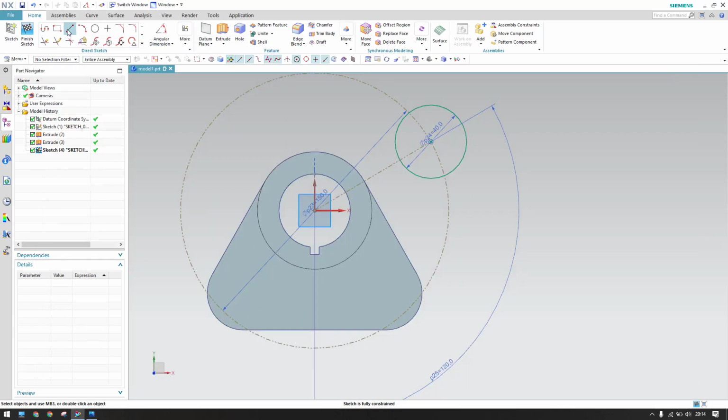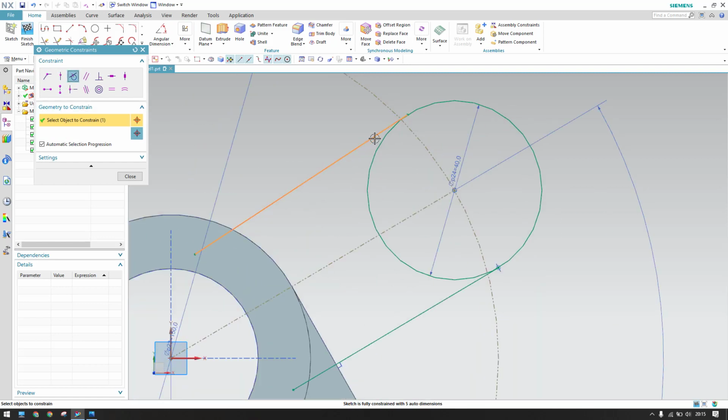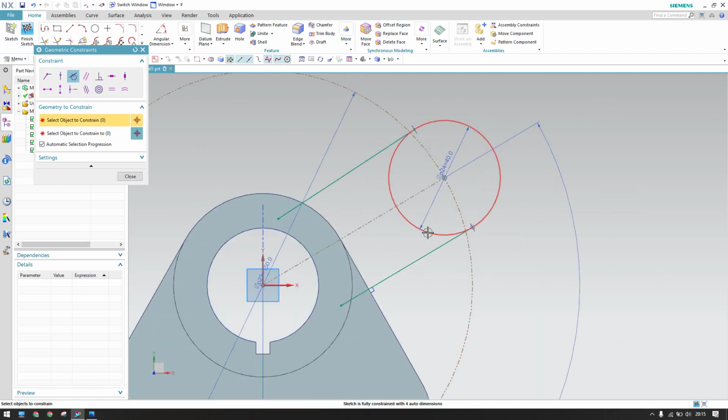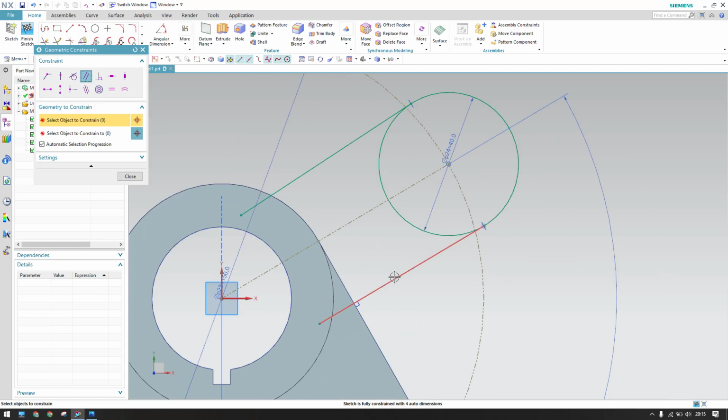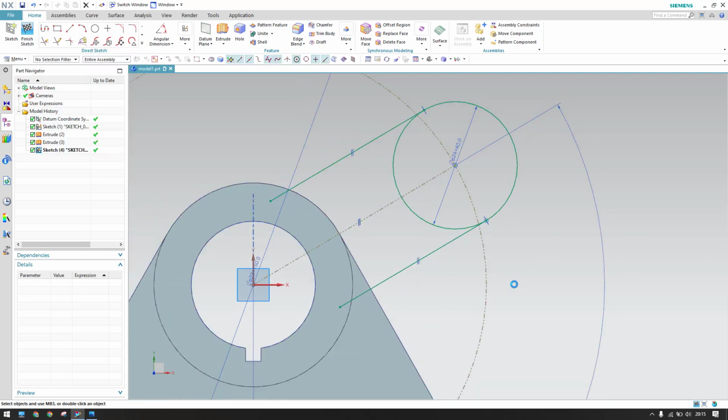Okay, so now we have to draw the tangent line, which comes and touches this circle. So let's go to line, and if you want to directly create a line with tangency, you just need to select this and give it like this. So it should always be tangent. Okay, so I'll just make a tangency here. Since I pressed Alt, it lost the tangency. So now these two should be parallel and these two should be parallel. So we just need to remove this extra line here.